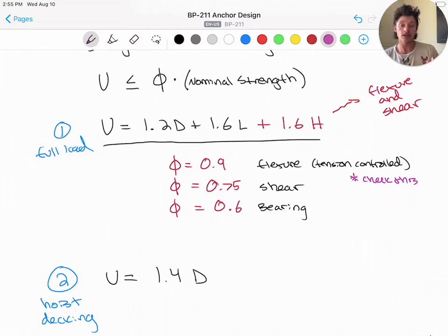We'll ignore serviceability design here, unlike in the towers, because the anchor is buried in the ramp. If cracking occurs and the anchor beam deflects a little bit, it will be supported by the ramp fill and overburden. So as long as strength requirements are met, we will consider this sufficient, although cracking in the anchor would not be ideal.